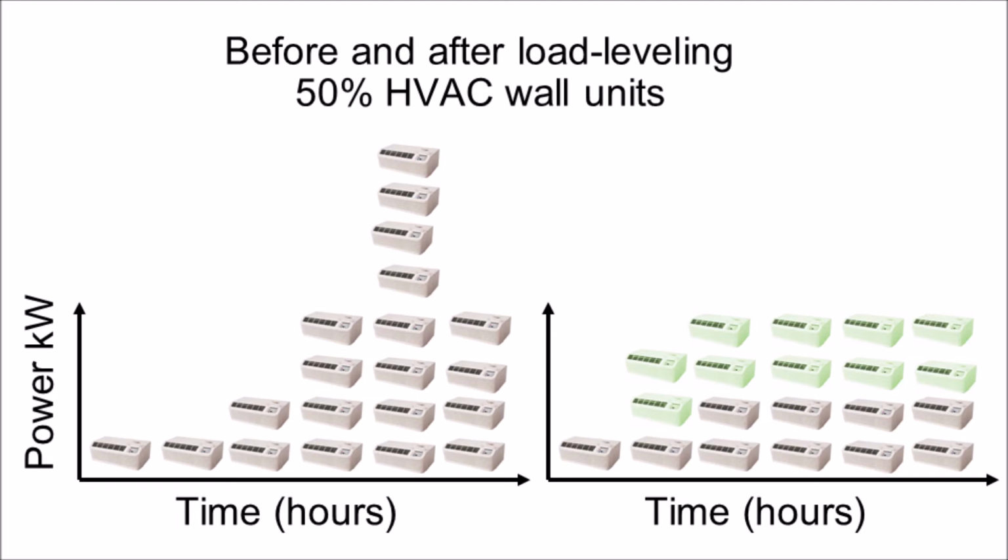Let's imagine that these are 5 kilowatt units each, most of which are running at full capacity during times of peak demand. Imagine if then we could reduce that peak demand by 4 air conditioning units simply by installing 10 controllers and then timing the units to power cycle in an organized manner.